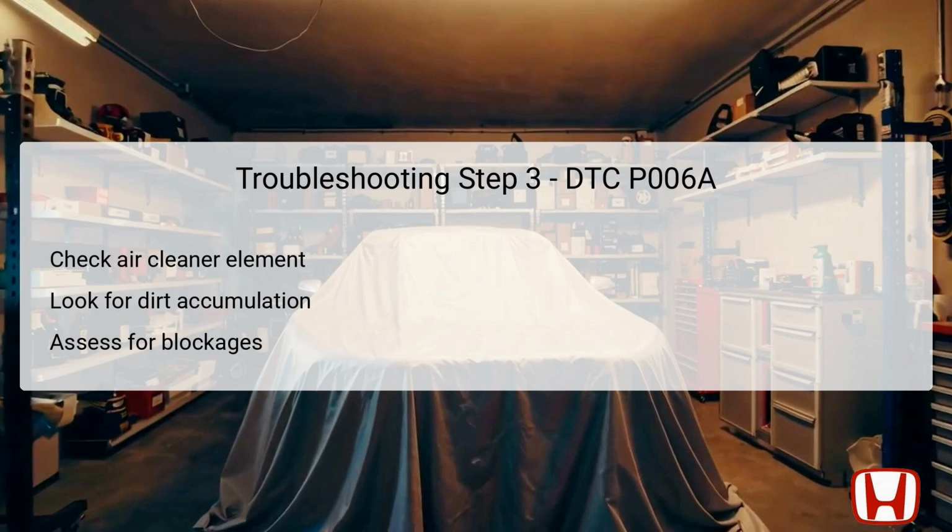In this third step, focus on the air cleaner element. Check for dirt and debris accumulation, as this can significantly impact airflow into the engine. A dirty or clogged air cleaner element restricts airflow, leading to skewed readings from the MAF sensor.